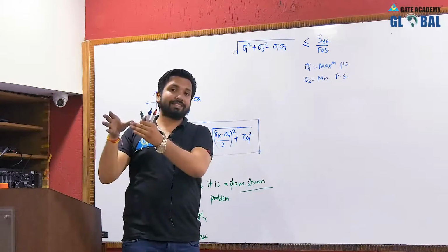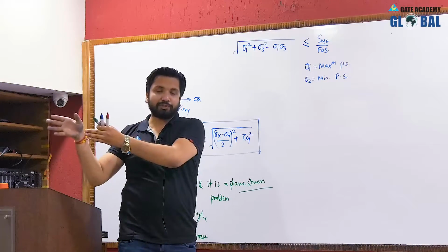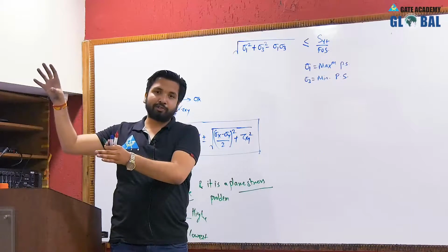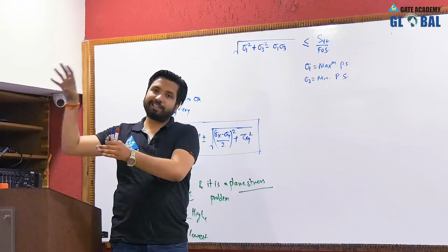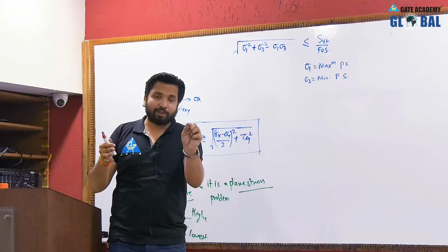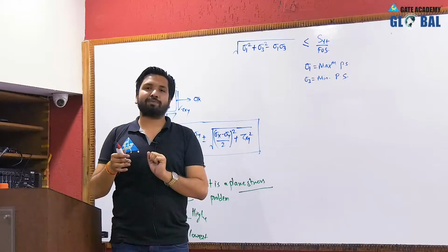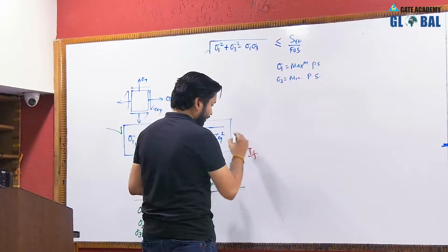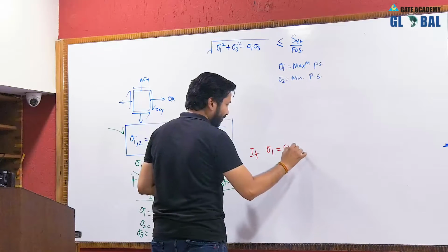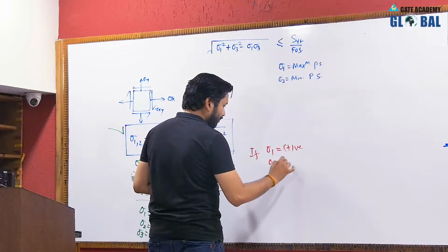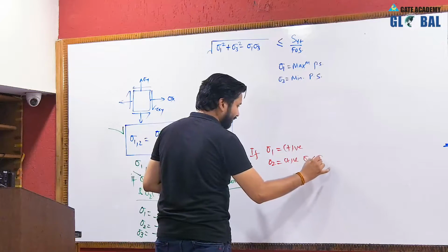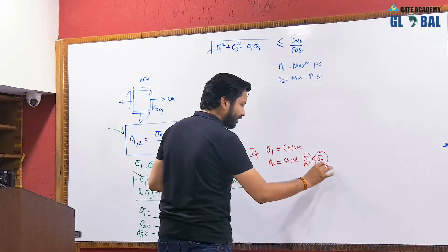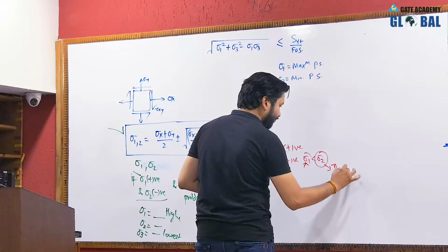Okay, but in the case where it gives you two positive values or two negative values, in the case of two positive values, the algebraically larger positive value will be the highest principal stress, and 0 will be the minimum principal stress. Okay, so if it is giving you sigma 1 as some positive value and sigma 2 as some other positive value such that sigma 1 is less than sigma 2, then this is not the maximum, and this is not the minimum principal stress.